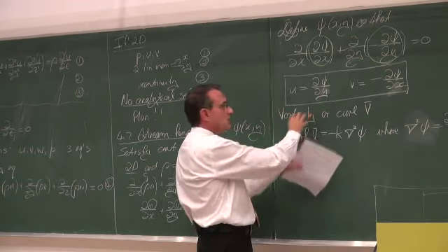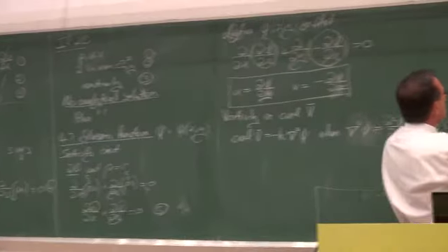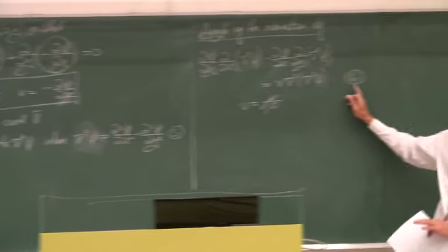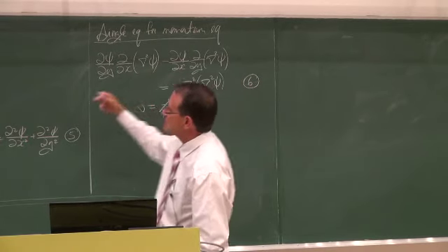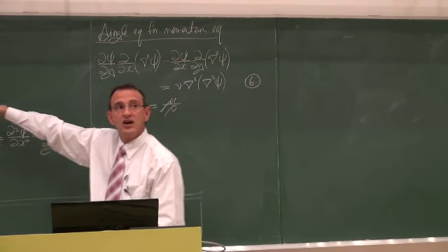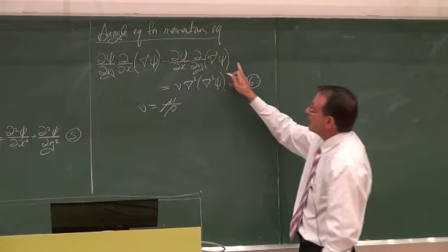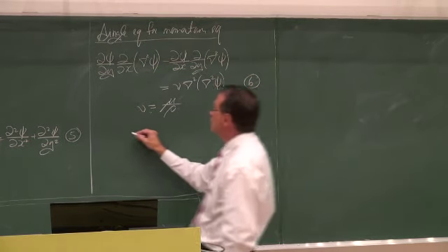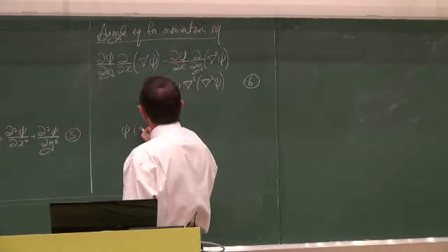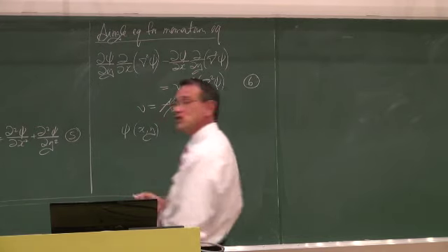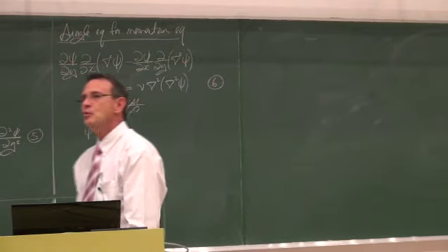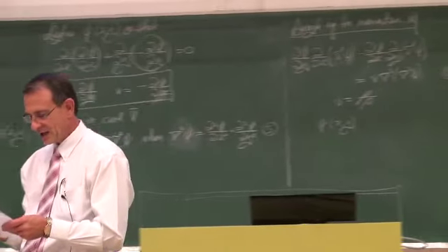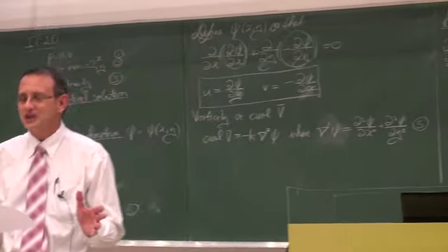Okay. Then some more mathematics, and the result is firstly that this stream function satisfies the continuity equation, but we've got an equation where we only need to solve the stream function as a function of x and y. Okay. And it satisfies the momentum equation. So that is now our new momentum equation.